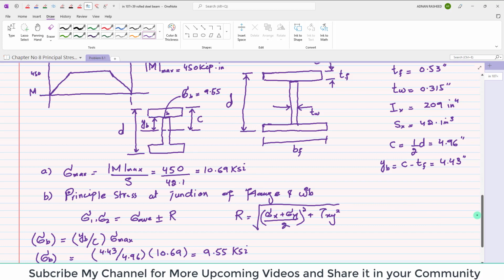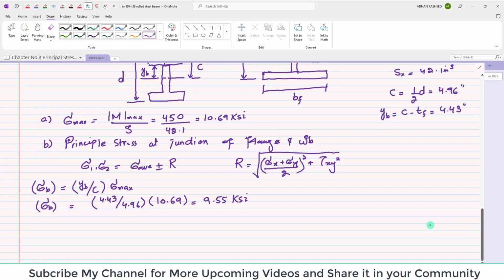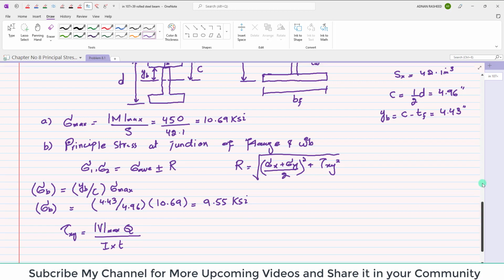Now we will find the shear stress, and we know that shear stress at this junction, tau XY, will be equal to V max into Q divided by I into thickness. Clear? So we have V max, which is given over here.